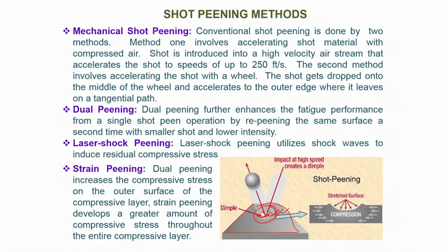The biggest advantage, always we should remember, is the creation of this state of compressive stress onto the surface, where the forces are acting towards each other. Hence if at all there is any crack or discontinuity created, first this crack has to see a situation where the state of stress is reversed from compressive to tensile, and only then can this crack further open. So this is a kind of preventive measure created by the state of stress, which prevents any kind of crack growth, particularly under fatigue or such operations.